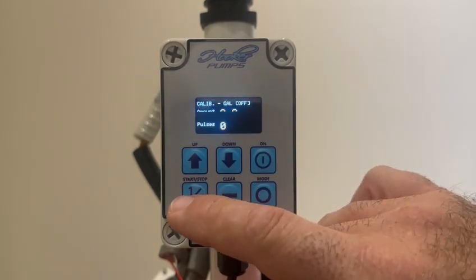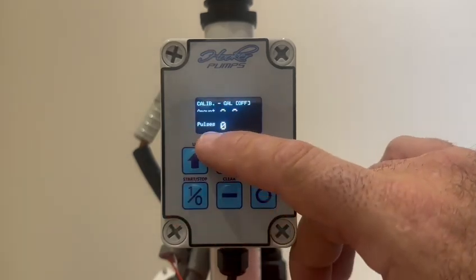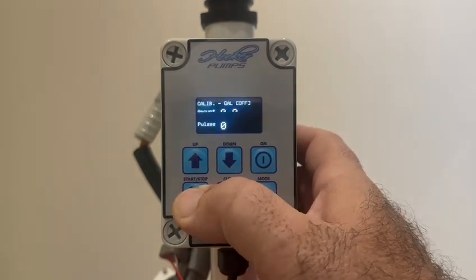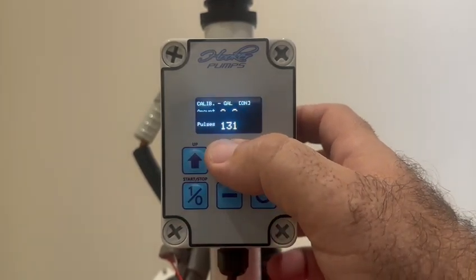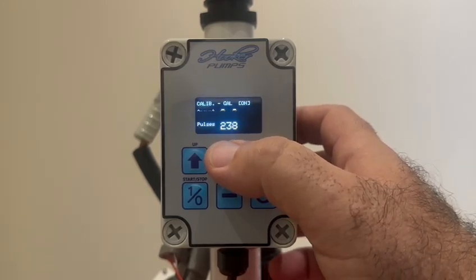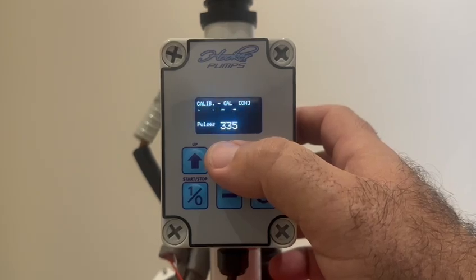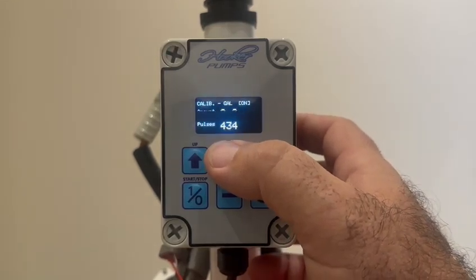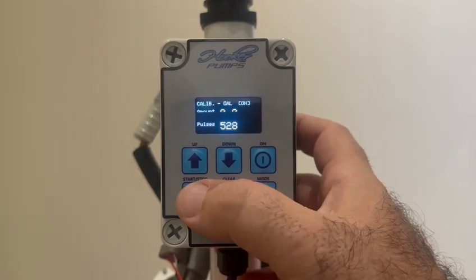What you want to do is press the start button when you're ready and fill that 5-gallon bucket up to that line. When you reach that line, that number will read approximately 1725. And we know when it reaches 1725, it's 1725 pulses for the 5 gallons. What you really want to know is what is 1 gallon's amount. So you're going to divide 1725 by 5, and you're going to get 345.